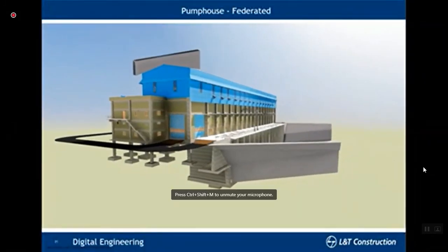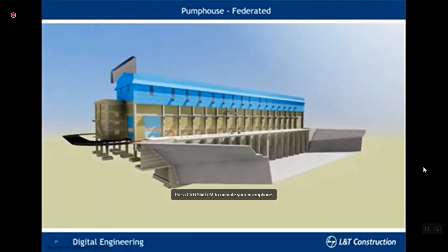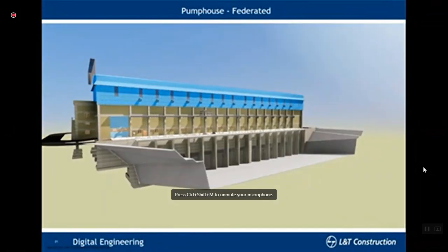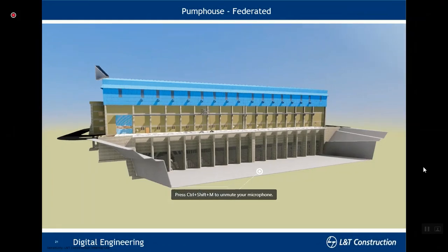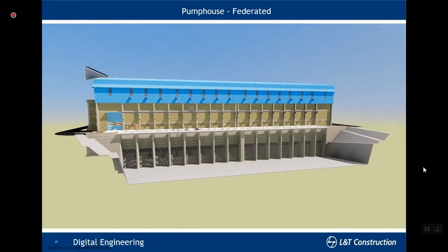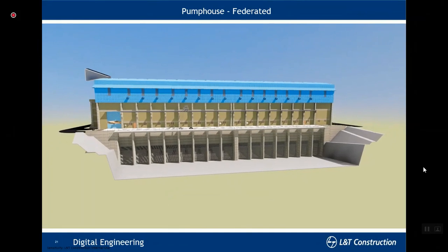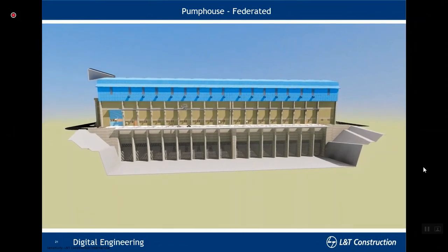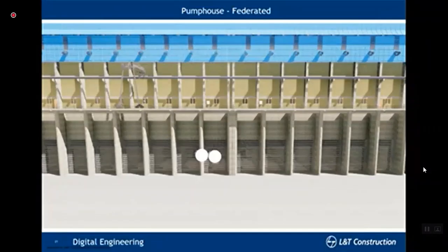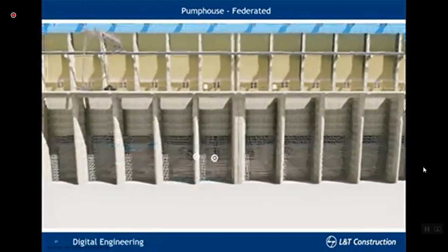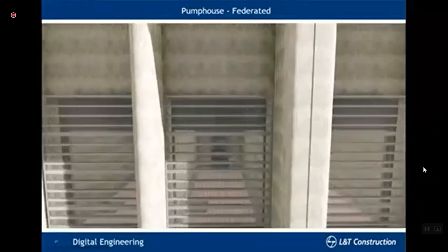Now, let us understand and look at various facilities. For example, this is the intake channel. This is where water flows through a canal or whatever. And if I go a little further, you will see the trash screen. What is a trash screen? A trash screen is something which stops the debris, like bigger waste. It could be some waste materials or sometimes animal waste, etc. And then you have the end wing wall.